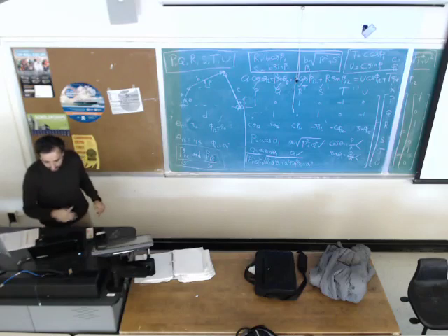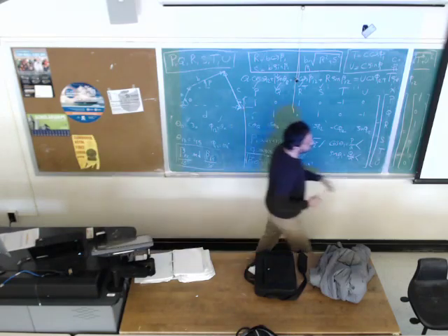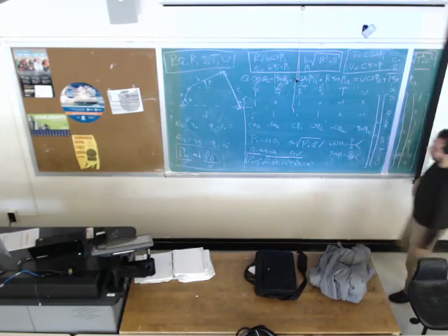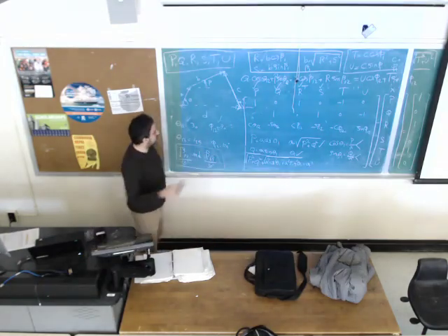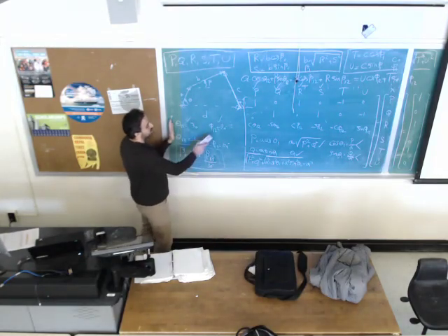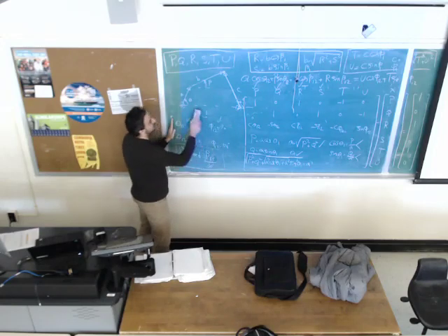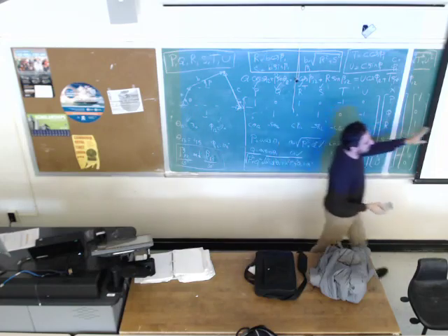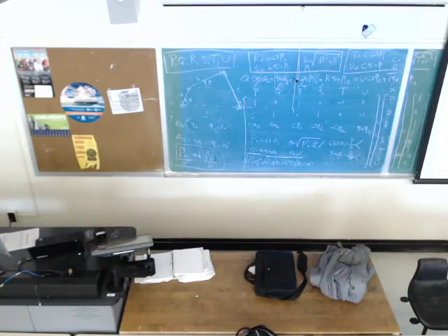All right. So the next synthesis problem that we cover is function generation for an offset slider crank. Here we are given the correlation between input angle and output angle. In offset slider crank, the input angle is there, but the output is the slider. So we are given the desired location for the slider.